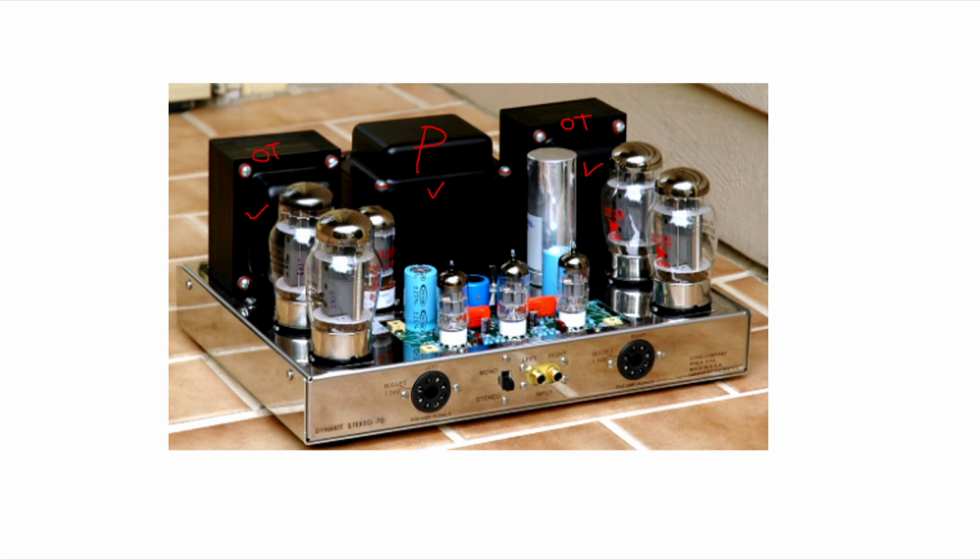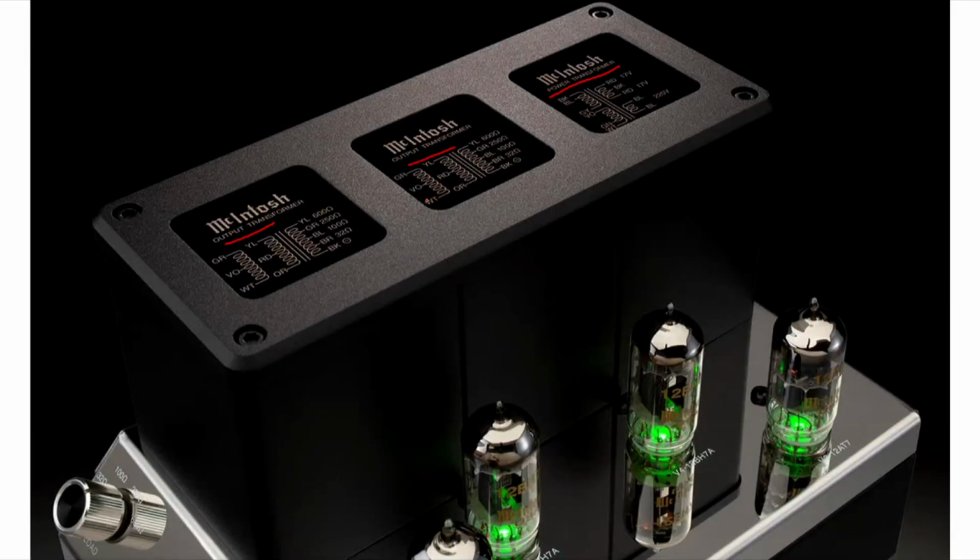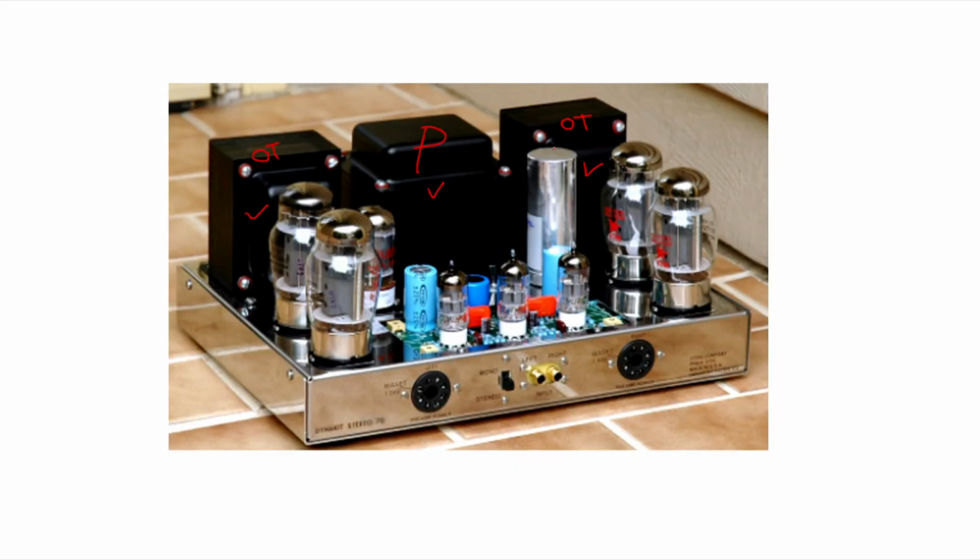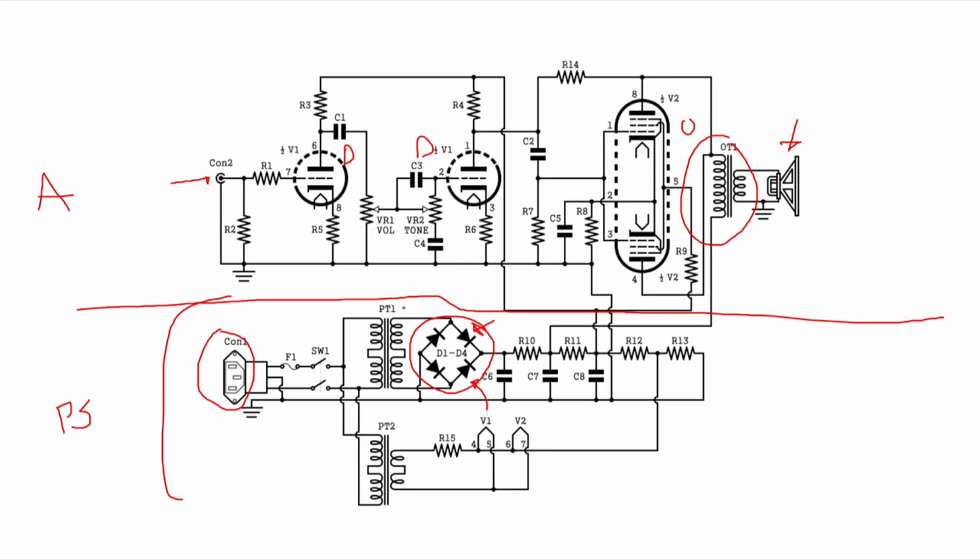in the circuit here. The power transformer right here is in the power supply. And its function is to take incoming AC, and if you're in America, let's call it 120 volts RMS from the power company, and to convert it, step that voltage up or down.